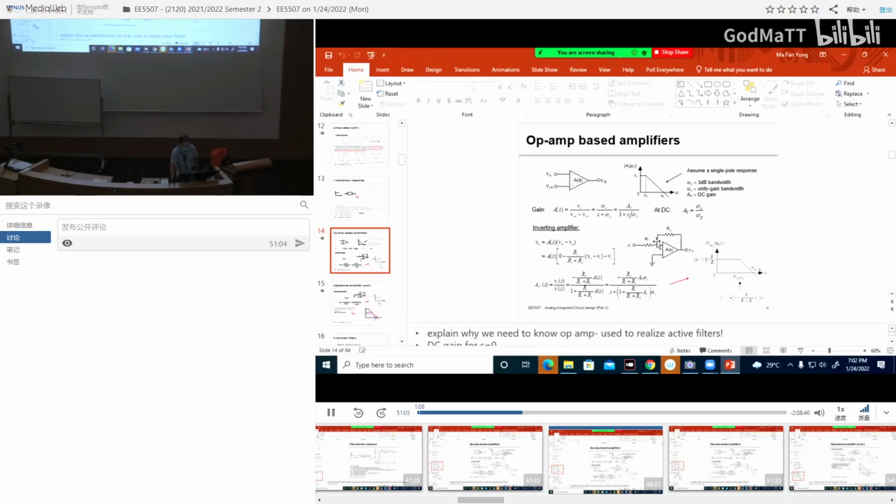You analyze this way, okay? So now, with the real circuit, this point is not ground anymore. What is this point? What's the voltage at this point? No, it's not zero. Zero is zero if you assume it's an ideal op-amp with infinite gain. Yeah, virtual short is you assume it's an ideal op-amp with infinite gain.